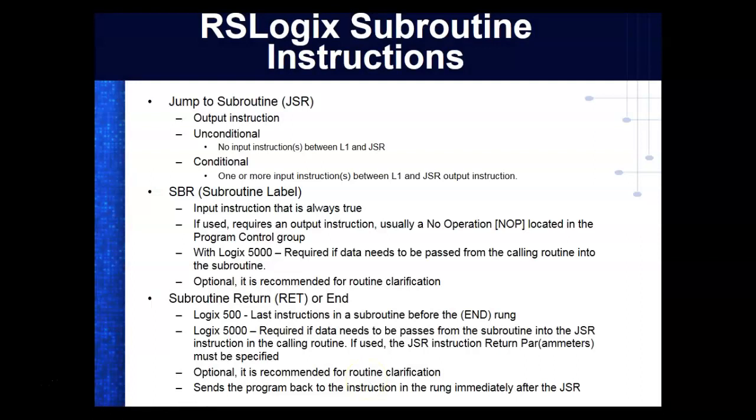Jump subroutine, output instruction is unconditional if there is no input instruction between L1 and the JSR output instruction. A conditional will have one or more input instructions between L1 and the JSR. We okay so far?